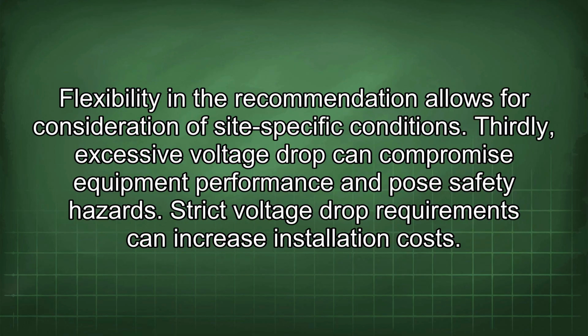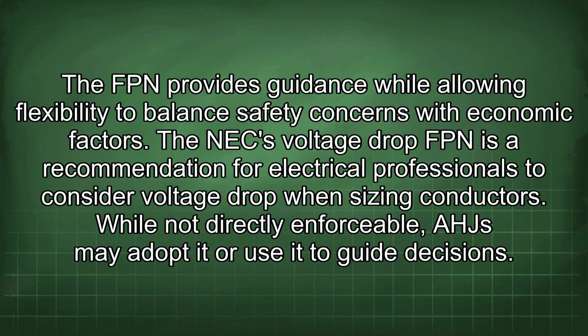Flexibility in the recommendation allows for consideration of site-specific conditions. Thirdly, excessive voltage drop can compromise equipment performance and pose safety hazards. Strict voltage drop requirements can increase installation costs. The FPN provides guidance while allowing flexibility to balance safety concerns with economic factors.